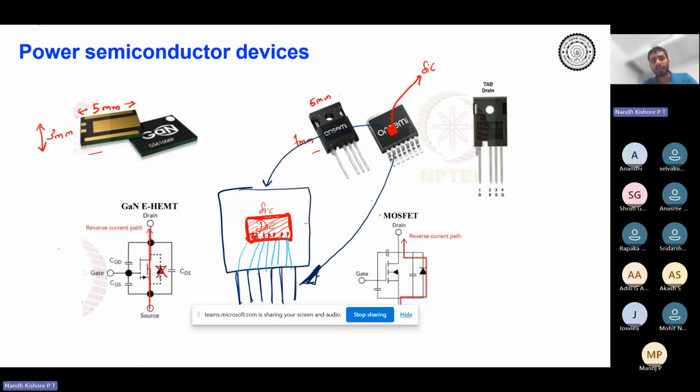As we were mentioning earlier, all the power losses are going to happen inside the channel, that is, inside the die. So in a very, very small area, there is going to be a huge power loss, and all the temperature rise we are talking about is going to happen in a very, very small area. That is the challenge. How do you take out that heat? In a very small area, there is a huge delta T increase, and taking out that heat is the challenge.